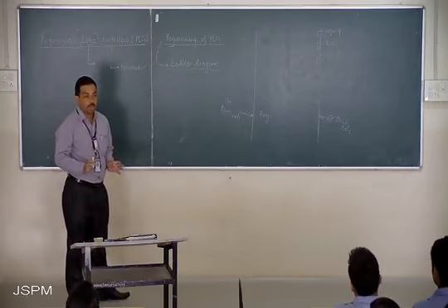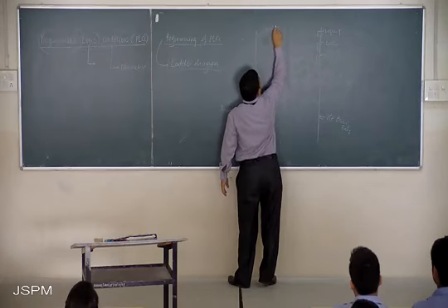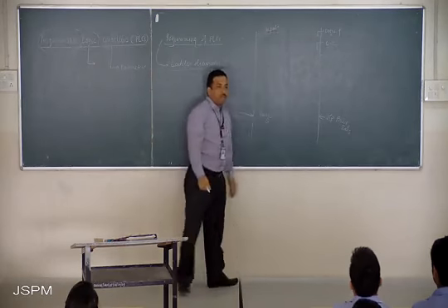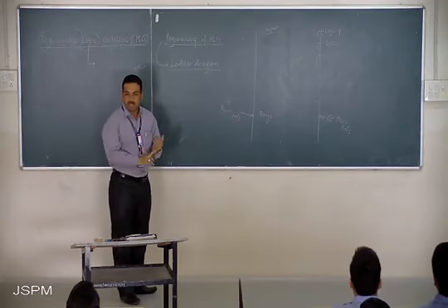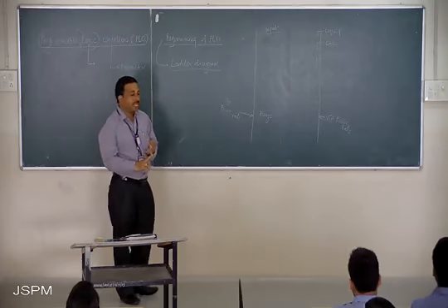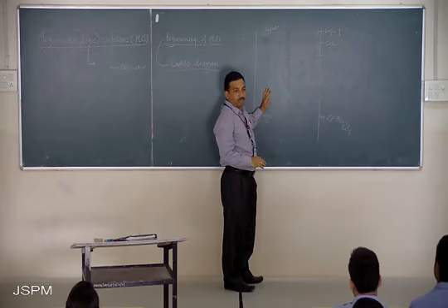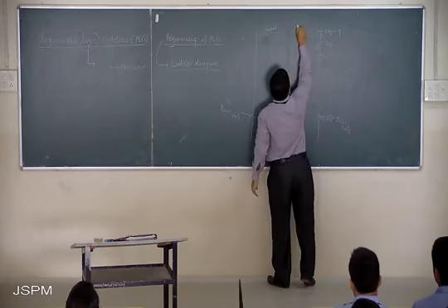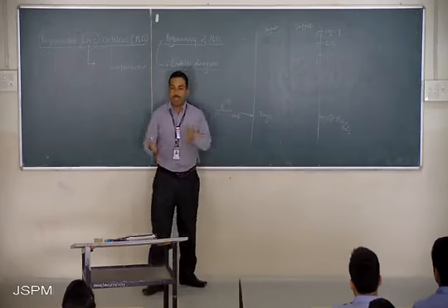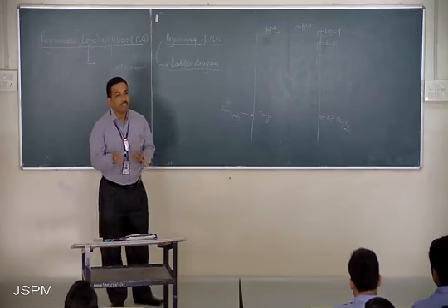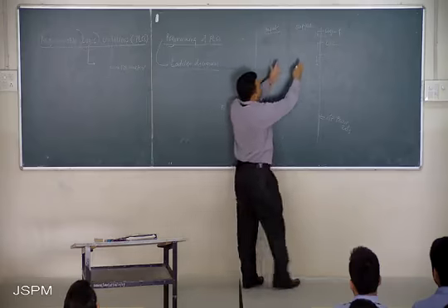See, this is a very important part. Now this section is called the input section. That means whatever component you want to represent as an input to the PLC, it may be some sensors, it may be some transducers, etc., all that should be graphically represented on the left hand side. And this side is called the output side. So whatever motors, solenoids, alarms, lamps, whatever output devices are there, they are represented on this region.